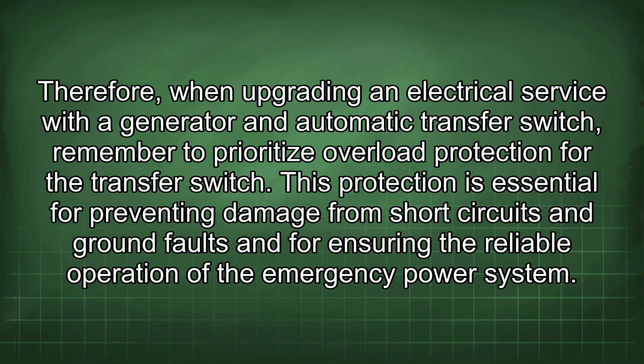Therefore, when upgrading an electrical service with a generator and automatic transfer switch, remember to prioritize overload protection for the transfer switch. This protection is essential for preventing damage from short circuits and ground faults and for ensuring the reliable operation of the emergency power system.